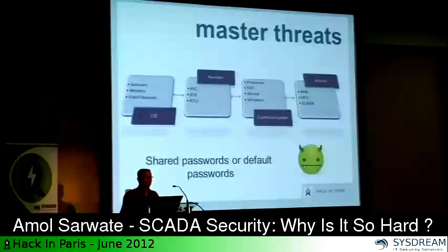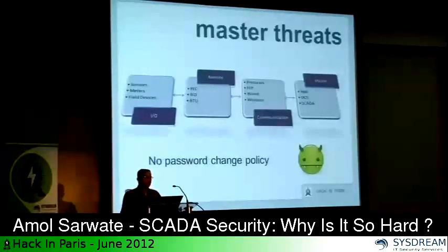There were shared passwords or default passwords. So if a virus like Stuxnet can identify that you are running a Siemens PLC, then it's very easy to go on the vendor's website, read the documentation, see what the default password is, and try that as the first guess if the malware is trying to brute force passwords. And no password change policy, and you know what a password change policy is.